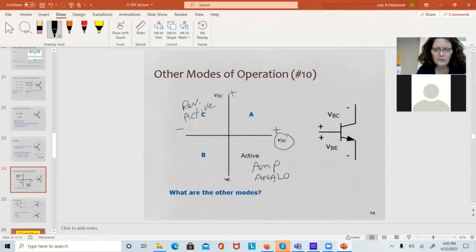One of the things you can do, when I was teaching a lab class that we used BJTs in, you could pretty much tell when somebody got an amplifier and their gain wasn't right. First thing that you checked is you went back to the data sheet and you said, which leg of the transistor is the base, which is the collector, and which is the emitter. And sure enough, they usually had them swapped. If it was acting like a switch, then it was one of the other regions of operation.